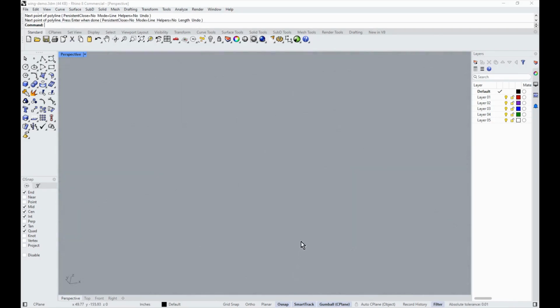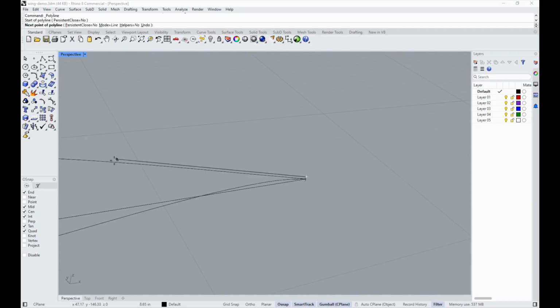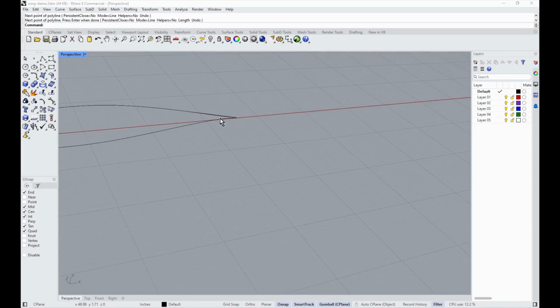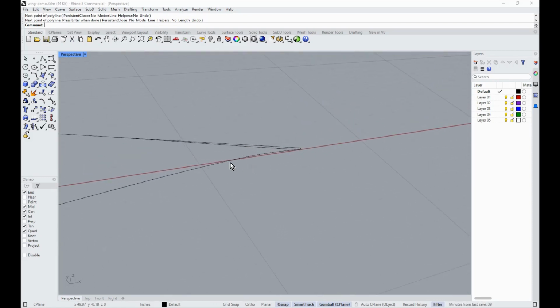So we did that to the upper surface. And we got to do this to this tip over here, tangent. So we have that established. And then let's see here how else to handle this stuff. So that's the upper surface taken care of. And we can do a trim right here, TRIM. Click on it, click on that. So now we've broken the airfoil like so, but we're going to need to join it.